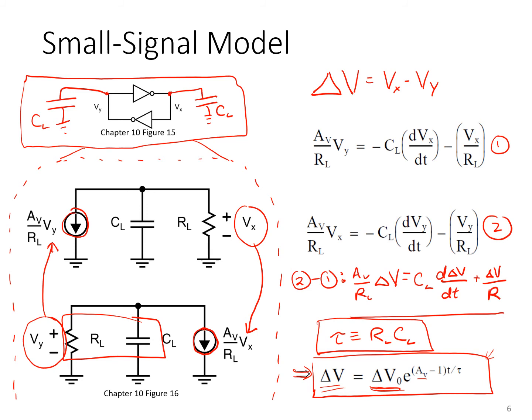And then finally, a small time constant associated with each of the nodes will also speed up the settling time at the output of the latch. And so again, this is just a generic picture of two back-to-back inverters, but if you examine them closely enough, practically all dynamic comparators will have a positive feedback core that can be cast into a model like this, and whose settling time therefore depends on the similar factors.